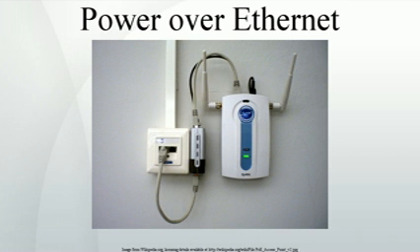Under Cisco's pre-standard scheme, the PSE switch will send a fast link pulse, FLP, on the transmit pair. The PD device connects the transmit line to the receive line via a low-pass filter, and thus the PSE gets the FLP in return. A common mode current between pair 1 and 2 will be provided, resulting in 48 VDC and 6.3 W default of allocated power.